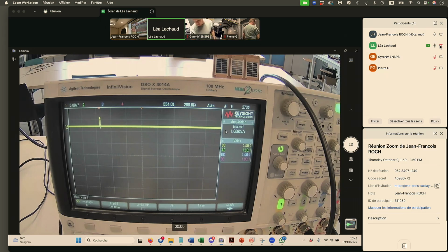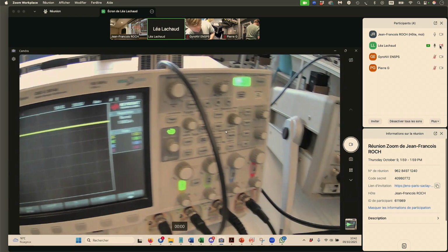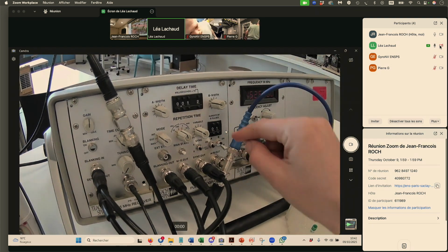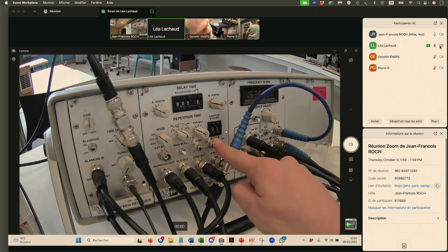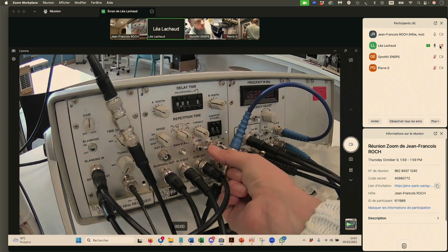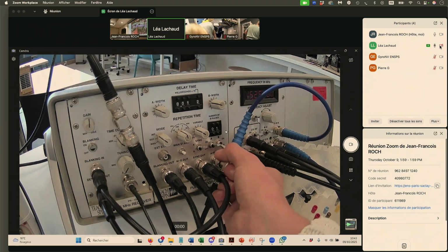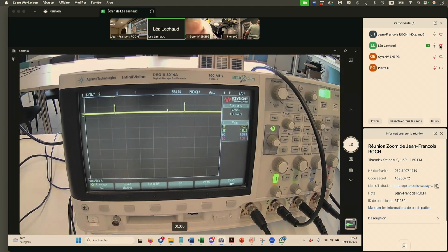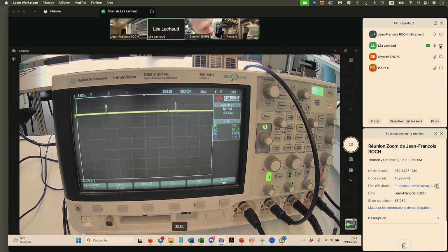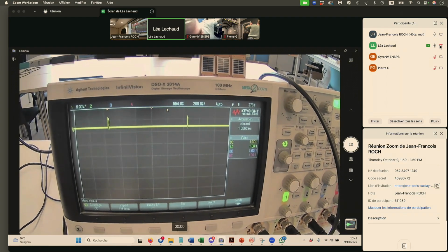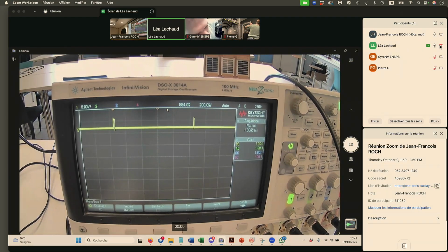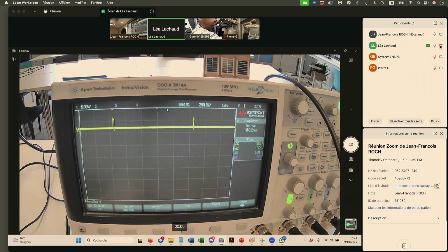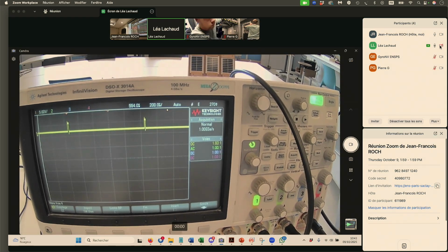So first, the first line here in yellow, the first signal I'm going to observe is the pulse sequence, right? So with the device, I can choose the number of pulses. I have two options. You see, here is the pulse A, here pulse B. So I can choose sending one or two pulses, right? I can also vary the width of each of them. Here you see I'm varying the width, meaning the length of the first pulse. I can do the same, obviously, with the second one.